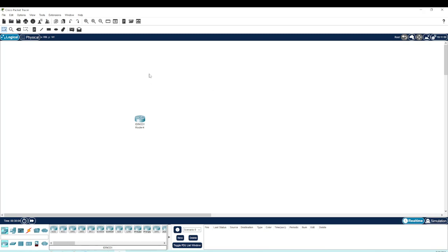So if you click on the white area outside of all the devices and then click on the delete key, you can actually come in and you see that it turns into the X again, and now you can actually point at the device you want to delete and be prompted. Now, again, if I hit cancel, it will go back into select. However, if I choose delete, notice that it stays the X even though there's nothing else on the screen. In order to change it back to select, we have to actually hit the select button.